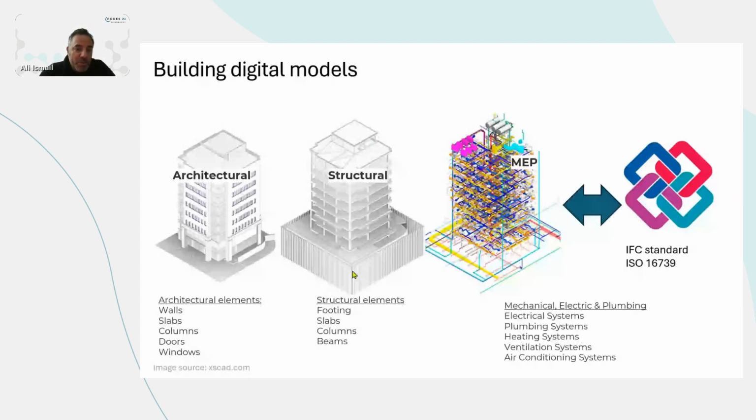This model could be very large and very complex and include huge information. How do we exchange this model? We can use a lot of software to design it. And the only common open standard for exchanging this model between different software, or to process the information in a standard and open way, is the IFC standard, which comes from Industry Foundation Classes, and it's ISO 16739.